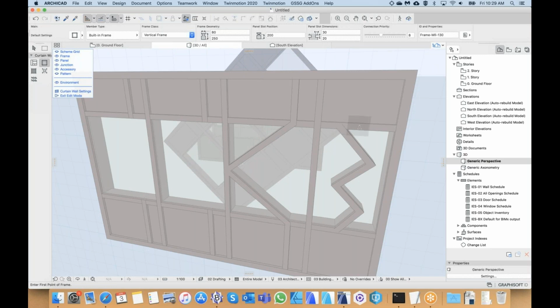So it's really important to understand the cursor situation. When I see a Mercedes symbol, it means I'm on an edge. And when I see a tick, it means I'm on a node. If I don't see either of those, then I'm not on an edge or a node. And during editing, the pencil will show me: if there's a line in the pencil, it means I'm on an edge. And if it's a solid pencil, then it's on a node. It's maybe a lot to remember. So just let me know how you go.